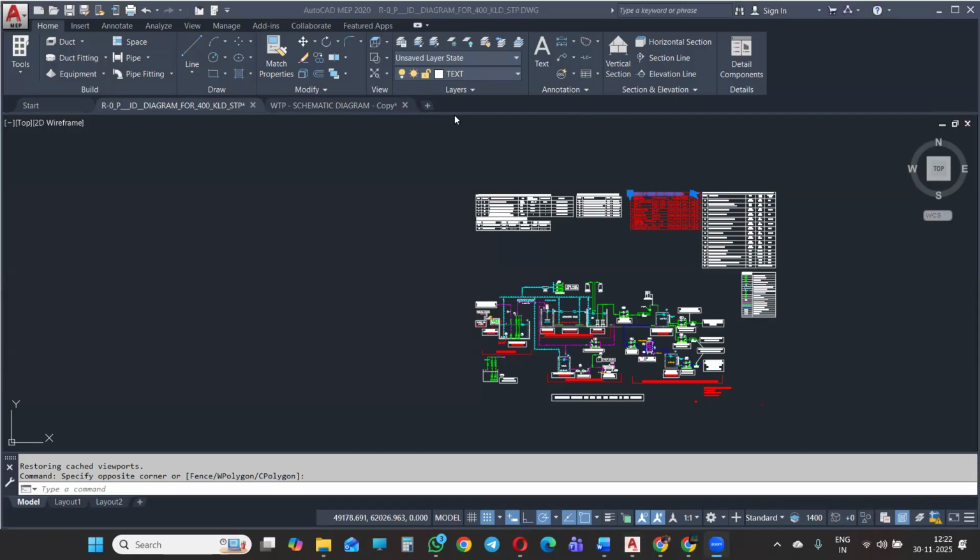Right, very right. Because if the bypass line is there, only then can you do maintenance in any tank. For a particular 1 hour, 2 hours, 6 hours, or 10 days, I have to shut down the STP or ETP or WTP. In that case, the bypass line will collect all the sewage going from the building and give it to that manhole, and that manhole will be pushed to the existing government connection or large sewer connection. Okay.